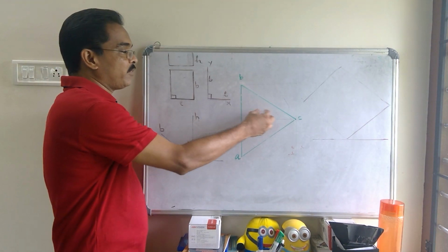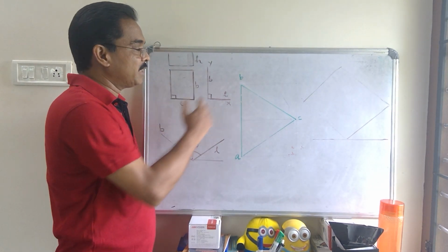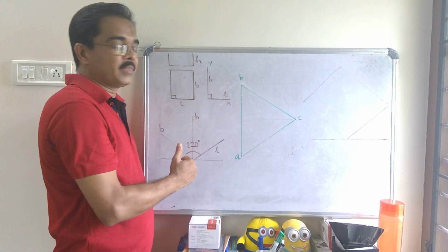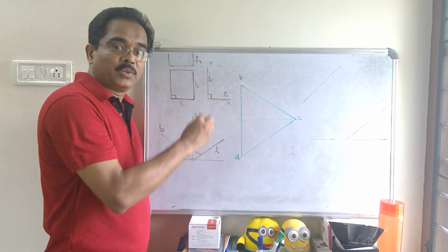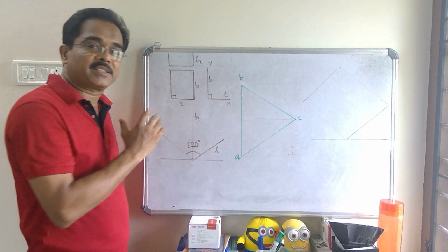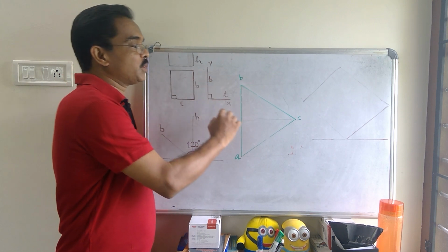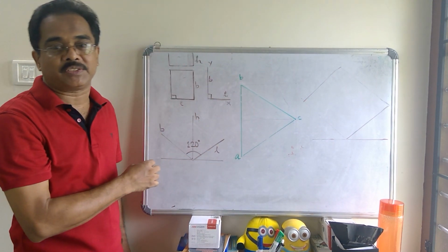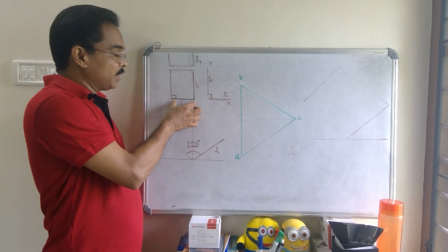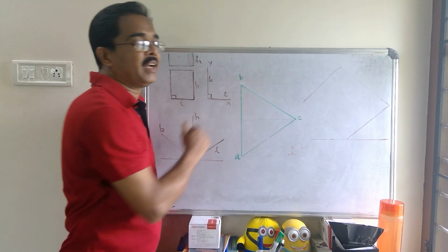But when you come to another solid or polygon, like a triangle, you can see that the sides are not orthogonal or 90 degrees. It has some inclination. The very important point to keep in mind while doing isometric projection is that only horizontal or vertical distances should be transferred to the isometric axis. You are permitted to transfer only horizontal or vertical distances directly to the isometric axis.